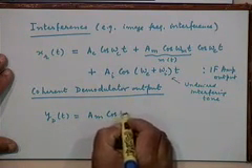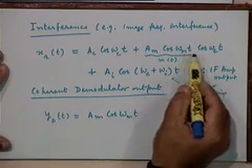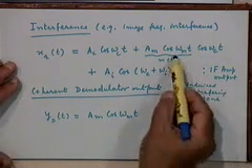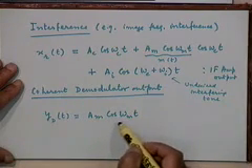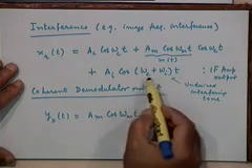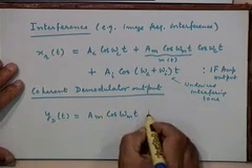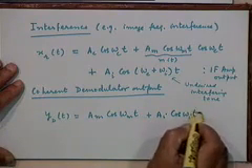I am not going through the details because these are things that you now understand very well. You are multiplying this with cosine omega_c t and then low pass filtering the result. You will get A_m cosine omega_m t, maybe with some scaling factor which I am ignoring here. But you will also get something proportional to A_I cosine omega_I t, right?